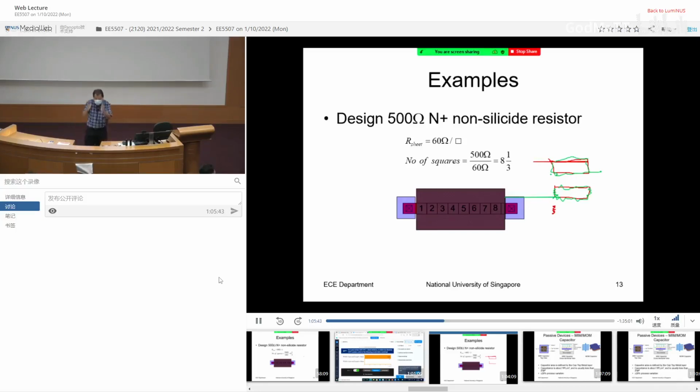Okay? But when you make the device very, very small, then all these jagged things get enlarged. They occupy a larger percentage. And that will cause mismatch, poorer matching. Okay? Then in that case, which area should I use? So if you actually look at the document of the process, they will tell you, if you want to achieve 1% matching, you need to lay out the device with certain area. The area need to be bigger than certain amount. So that is how you pick the area.